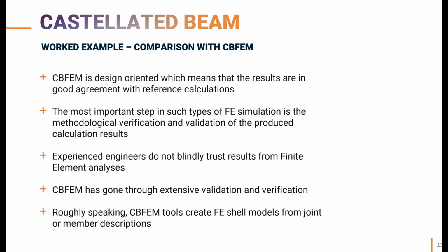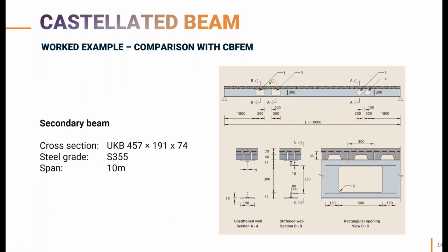Briefly, what we call CBFEM components are fine-tuned finite element sub-models that reflect the behavior of plates, bolts, welds, and other components described in the code. And we have proved that these finite element sub-models, or CBFEM components, provide very good agreement with the code.